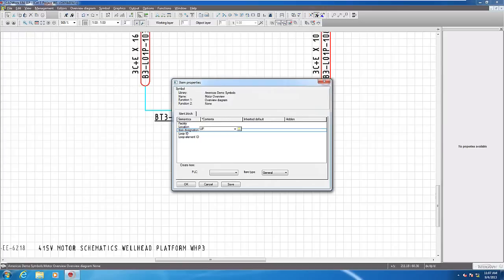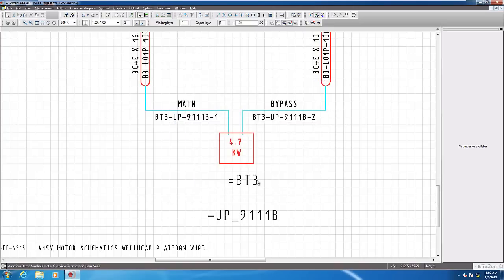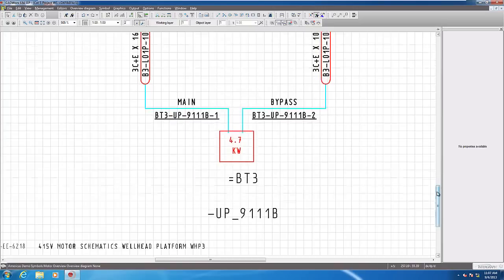And I can go ahead and make an item designation assignment, in particular the one that I pointed out at the beginning of this. And again, you've got to make sure that you set up all the appropriate information as CADWorx E&I sees it. So when you do that, you can immediately begin to see the data come in.